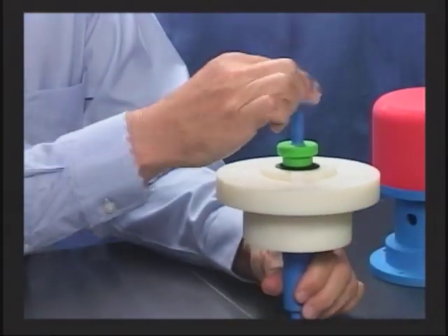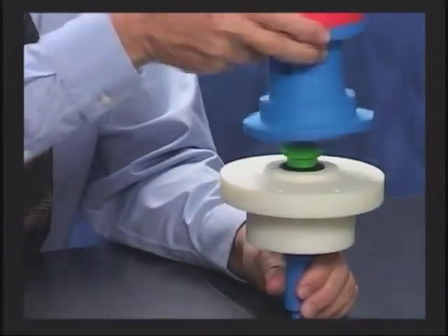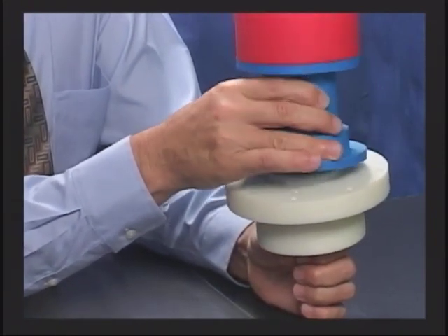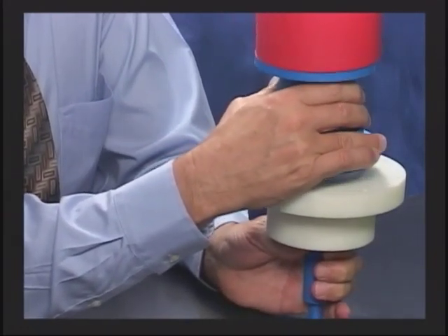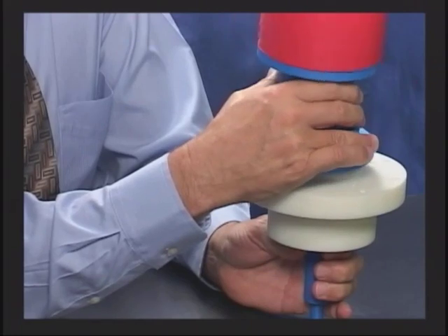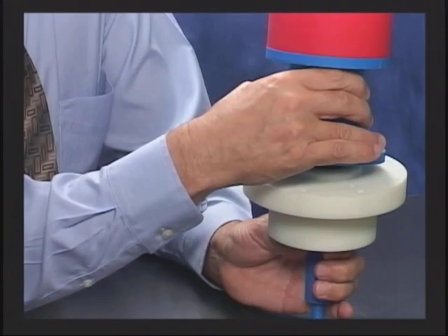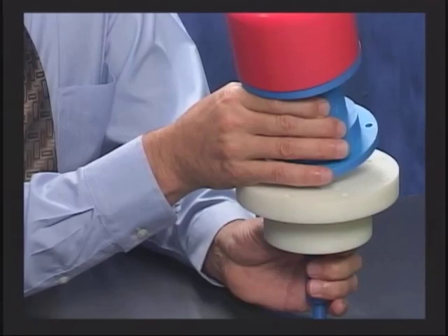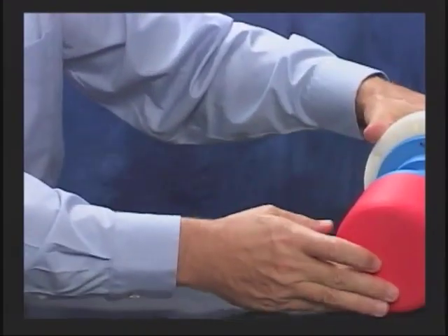Let's take a look at our model here again. And we had the axis. This was our datum A dash B, and we said that that face could tilt. Now when it tilts, you take that electric motor and you put it on top, and see what happens as it tilts. It tilts back and forth. If it tilts this way, remember, within 5, it could also tilt this way within 5. You notice what it's doing is tilting double that on a diameter, because it tilts back and forth. It could go off by 5 this way, and it could also tilt this way within 5. So as it does that, that's why we have double that amount on the diameter.